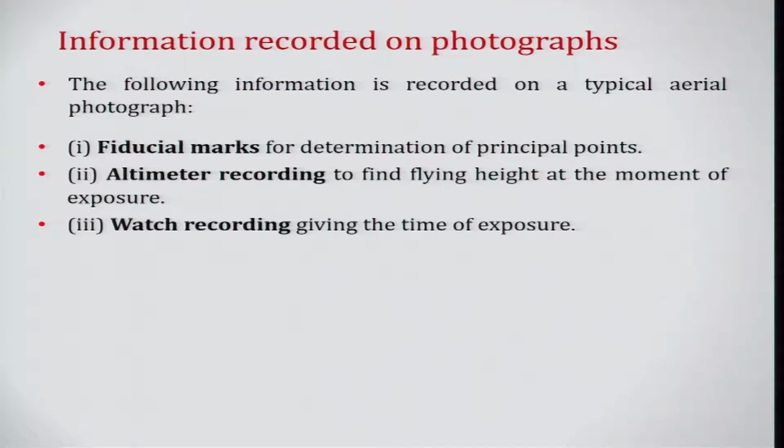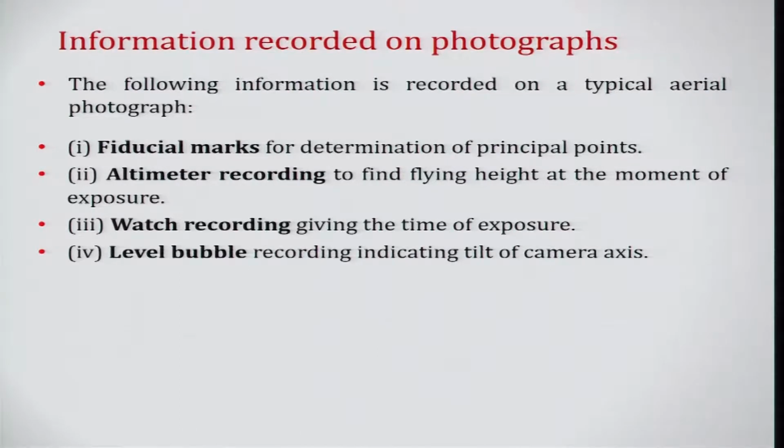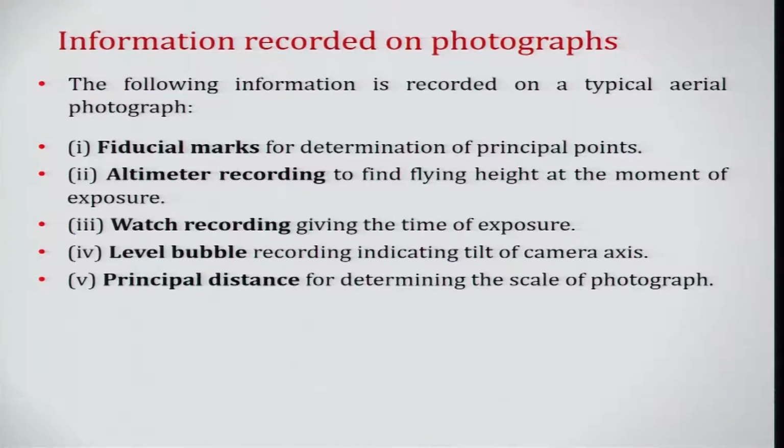Then the watch recording, that is the time at which you have taken the photographs. Then the level bubble, whether your camera was tilted or absolutely vertical. Then the principal distance for determining the scale of the photograph. So, you can also calculate the scale if you have almost vertical photographs, and you can compare either based on that information or the object on the ground